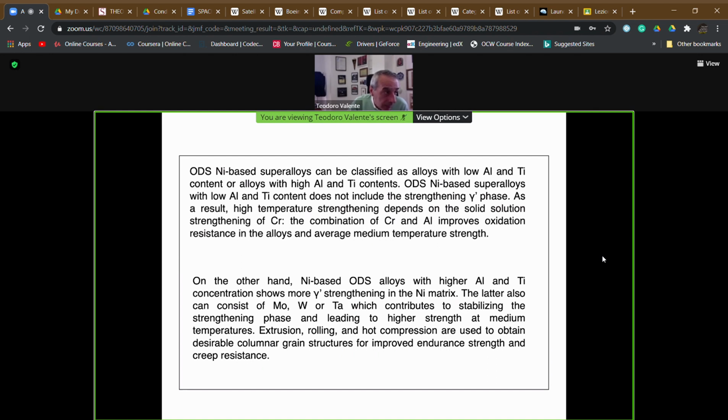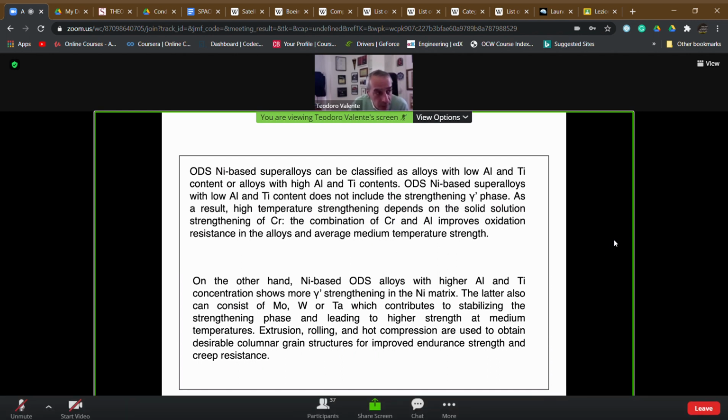Thus we can say that nowadays, due to the possibility offered by simple nickel-based superalloys to have single crystal fabrication technology, not offered by ODS alloys, the nickel-based superalloys are still the most important materials for high-performing, very highly stressed turbine blades, instead of ODS.